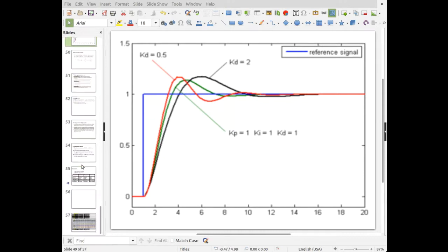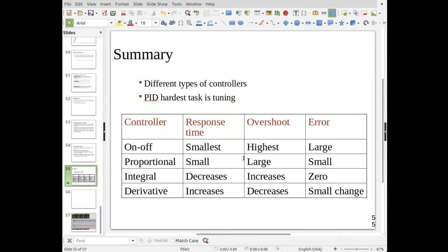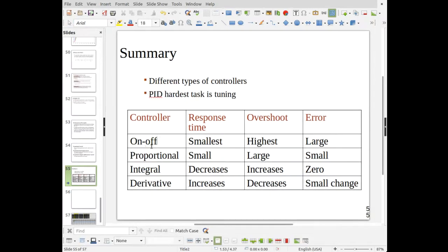Okay, so those are our proportional, integrator, and derivative pieces. I tried to give you a table here to summarize these. The first one here is what we called the bang-bang controller, kind of what we did in the PLC1 class, with just a high sensor and a low sensor, and just turn it on or off, and that was about it.